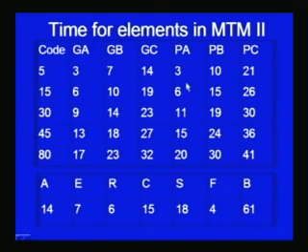In the same way, for the put basic motion, with the increasing degree of difficulty, time increases from 3 TMU to 21 TMU, and increasing distance also indicates increasing time required for put of the A category.